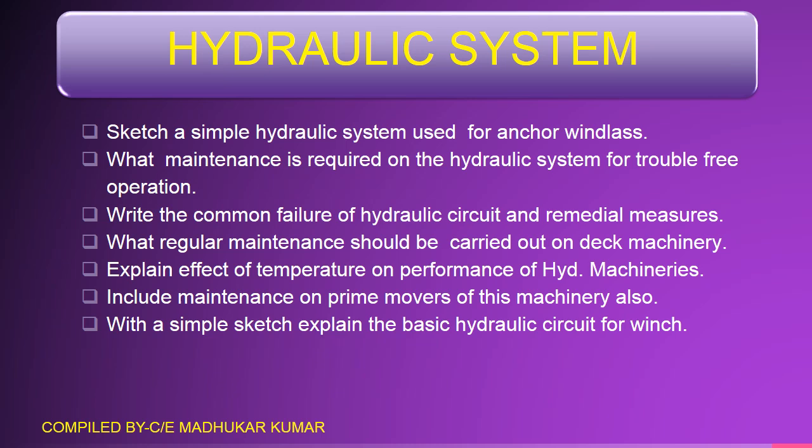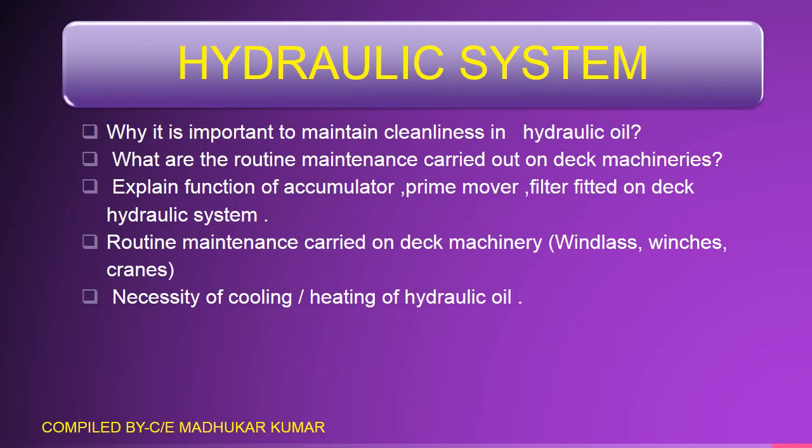Explain effect of temperature on performance of hydraulic machineries. Include maintenance on prime movers of this machinery also. With a simple sketch, explain the basic hydraulic circuit for winch. Why is it important to maintain cleanliness in hydraulic oil?